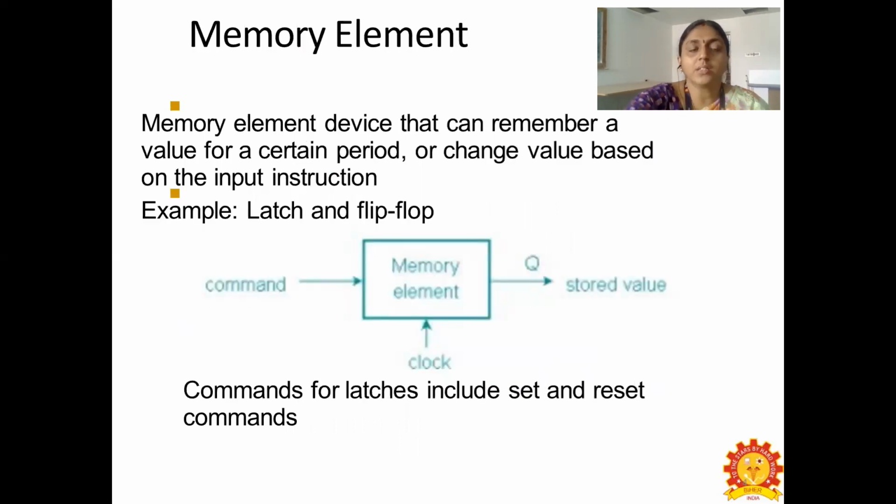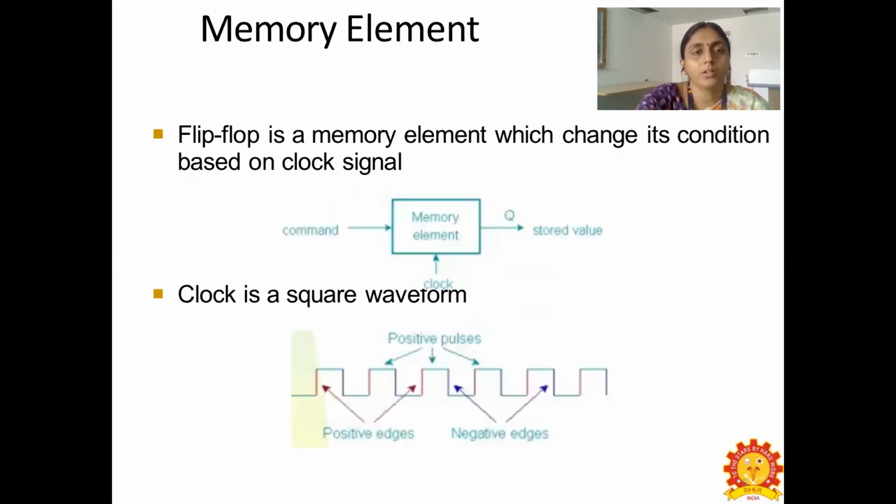Now we will see the memory element, a device that can remember a value for a certain period of time or change the value based on the input instruction given to the circuit. In latches and flip-flops, the commands for the latches include set and reset commands. A flip-flop is a memory element which changes its condition based on the clock signal given.